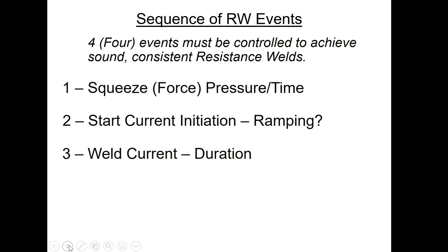And the weld current duration. How thick is it? And how long are we going to weld it for? Based on that, there are a number of factors, like your choices for resistance welding caps and so forth, that will have to be a part of that as well.